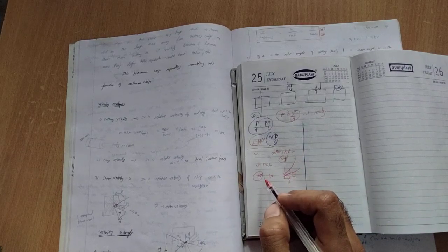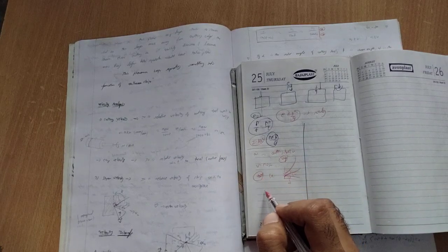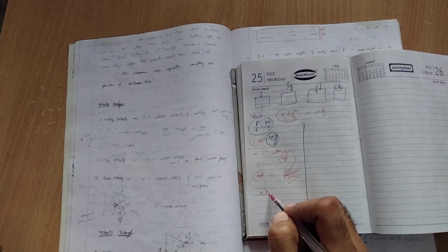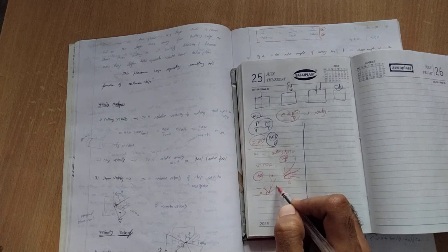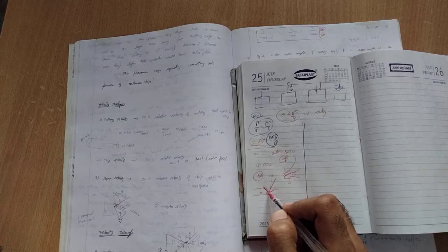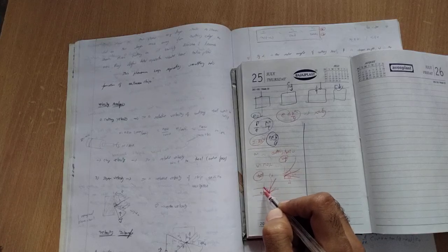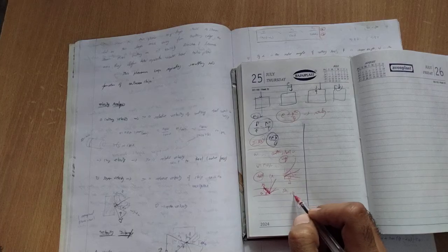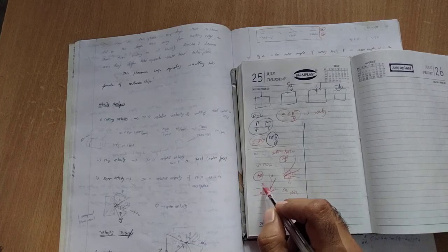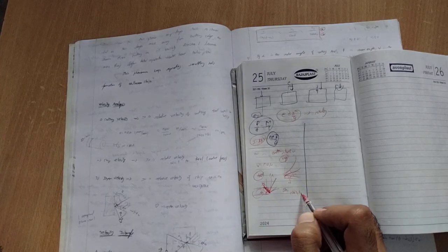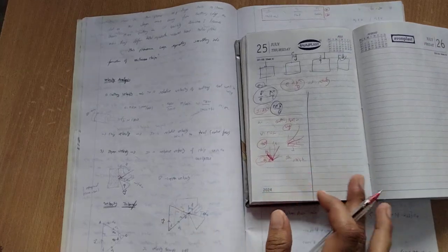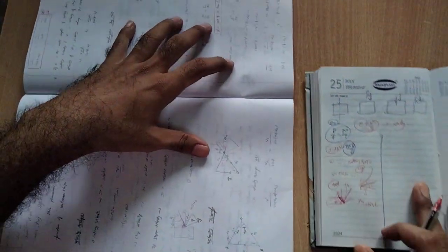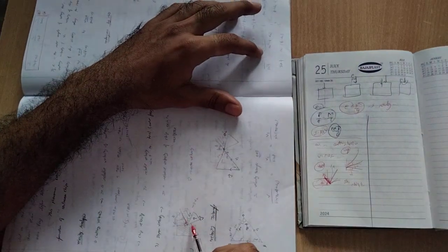And the shear velocity: according to the shear, it will be like this. This is the shear angle, and here the chip will move. This is the cutting tool. This is the shear plane, and along this shear plane the velocity moves like this. It is called shear velocity. It is the relative motion between the chip and the workpiece. The chip moves here, and this is the workpiece.